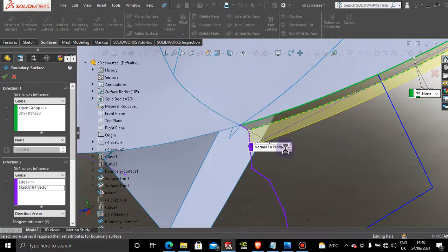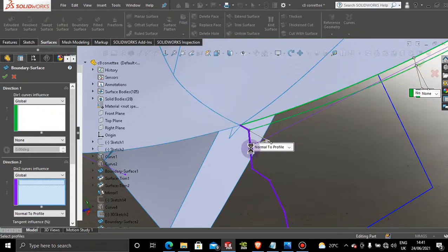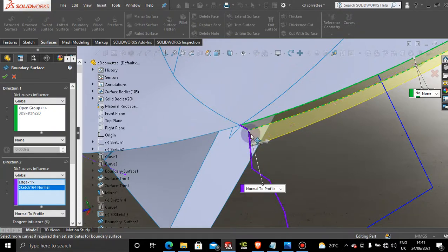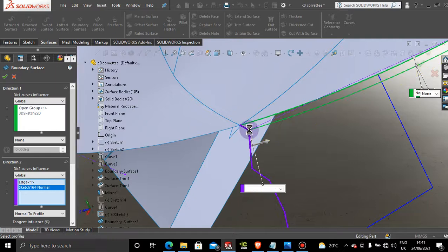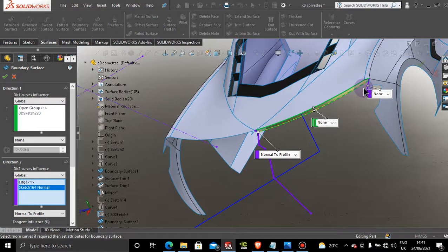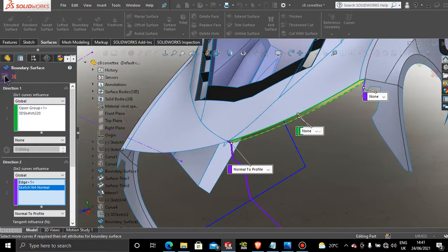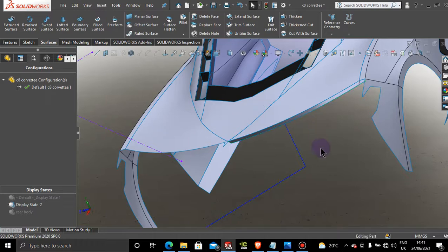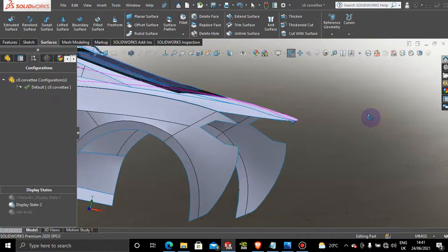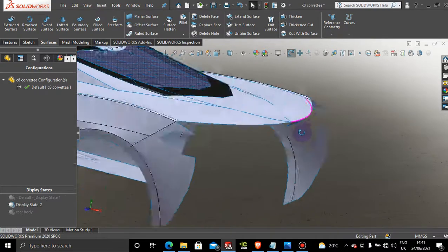No, we don't want to add any tangency on this face. So I want to pull this point all the way into this corner here, and that pulls the other side in as well, and that creates our surface. So press OK. And our surface body here is getting complex, and that's exactly the surface we're looking for in this area here.